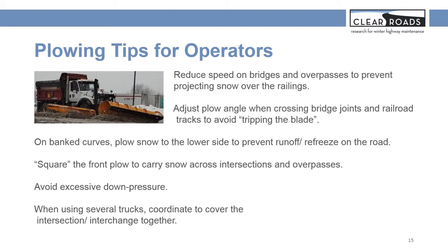Next are some plowing tips for the operators. For example, square the front plow when crossing intersections or overpasses, and on elevated curves, always plow the snow to the lower side to prevent runoff and refreezing.